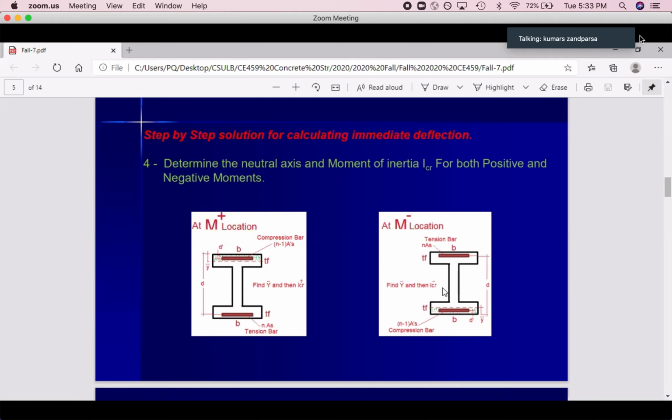Another part, if we have negative moment, so compression at the bottom, so concrete in compression, rebar in compression, A prime, rebar in tension, AS. As you can see, just rotate this one 180 degrees and you will reach this. That's it.